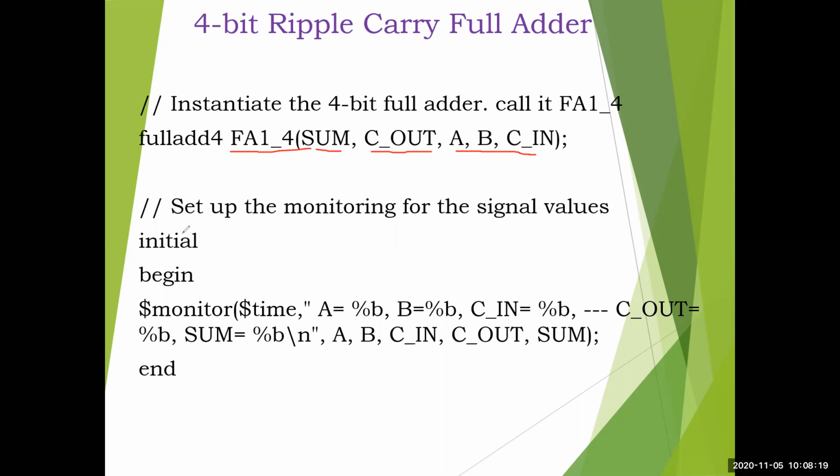Next we have to write the monitor statements. When we write monitor, it should be written in a separate initial block, with begin and end, and inside that we write it here. So display, not like that. $monitor is the system task. Just space, I gave a typing mistake; no space is required. Okay, let it be the same.